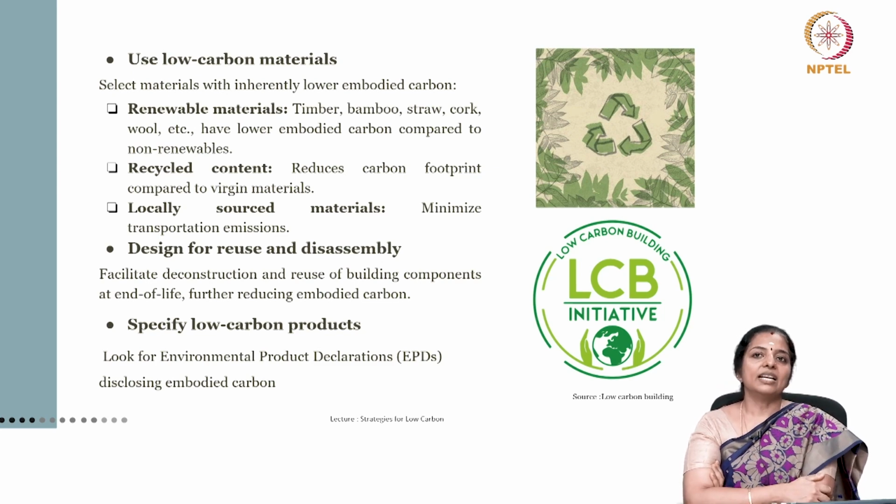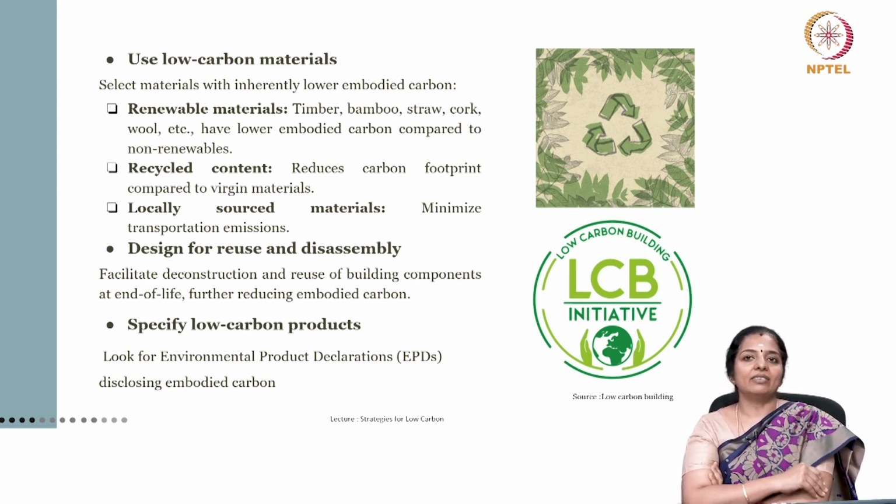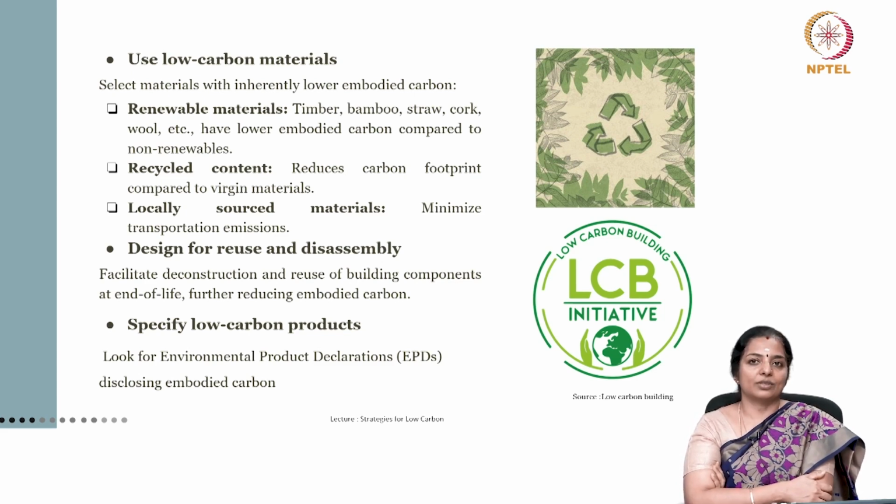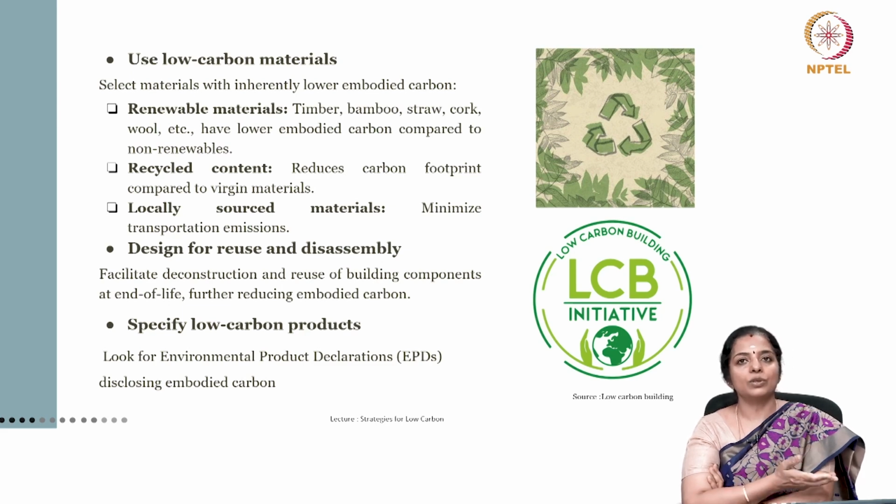For example, instead of a XPS insulation, alternative insulation can be used, which will have low embodied carbon. Now, steel sourced from an electric arc furnace and made with high recycled content will have a lower overall embodied carbon as compared to steel which is got first time.